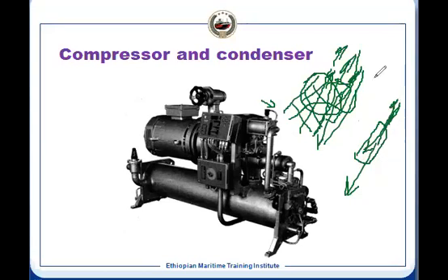And this will depend on the outlet temperature of our AHU. That we have seen, there is a temperature sensor which will sense the deviation between the measured value and the set value. Accordingly, if the measured value is higher than the set value, it means more cooling is required. The capacity will increase, and the mass flow rate through the evaporator coil will be increased. The mass flow rate part is exactly the same whether it is reciprocating or screw type. Only the screw type we use where large capacity is required. There we use the screw type.